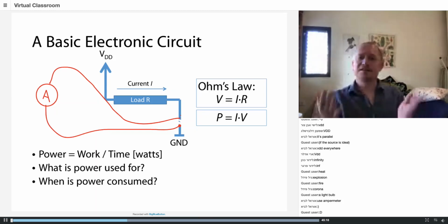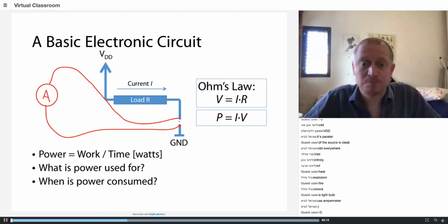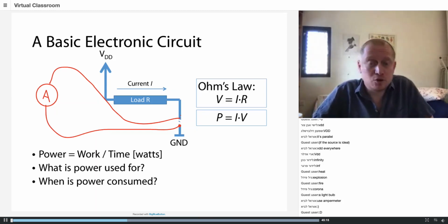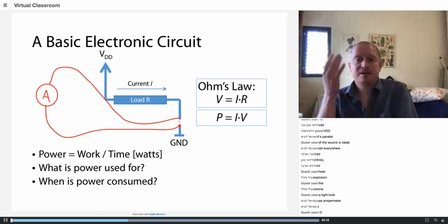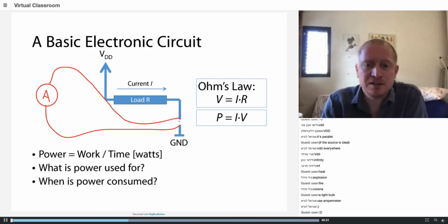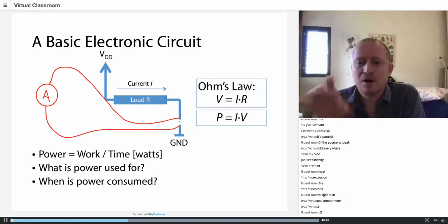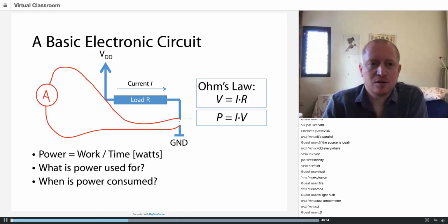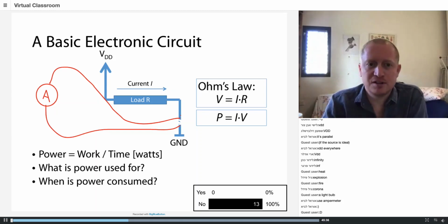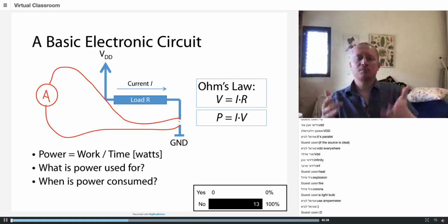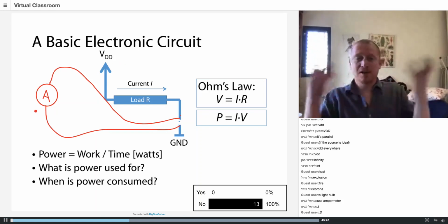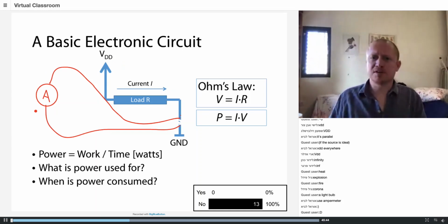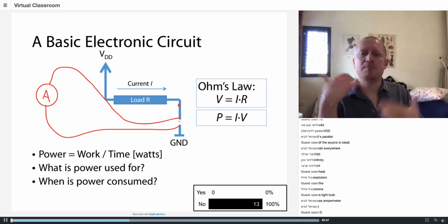And now this is a voltage divider. So if you do a voltage divider with a short circuit, will this change the voltage drop on the load? Will the voltage drop on the load change because of what I did now? So the answer is no, it will not change. Why won't it change? Because this is like a short circuit. I just showed you a short circuit. It doesn't change anything. So the voltage drop doesn't change, the current doesn't change, and I measured the current.